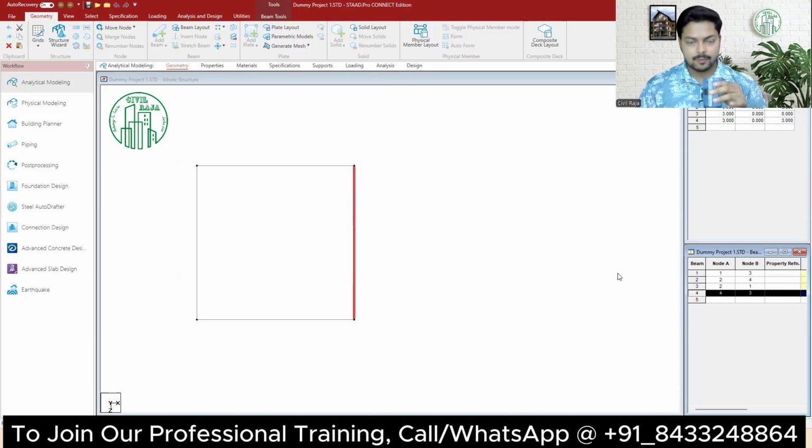So this trick will be helpful to you whenever you are selecting any particular beam, because in the warnings or the errors you will get messages that this particular beam is failing, or this particular beam is not good enough to accommodate your reinforcement. So warnings like that will be showing. So you can simply select it from there.